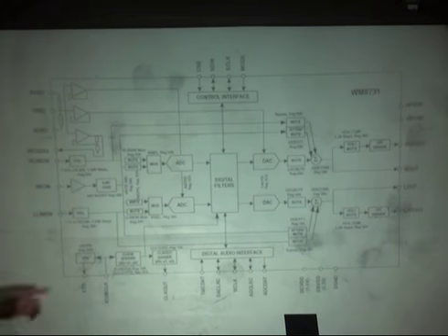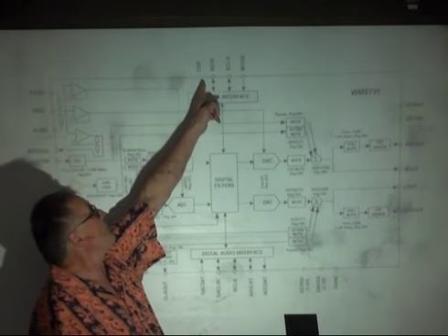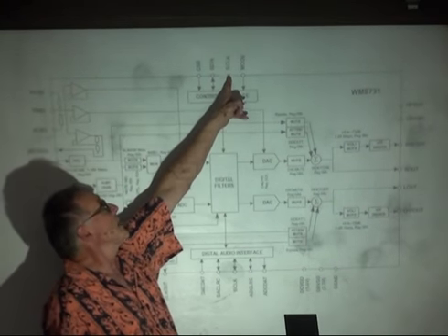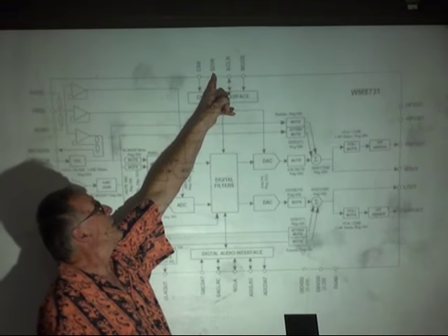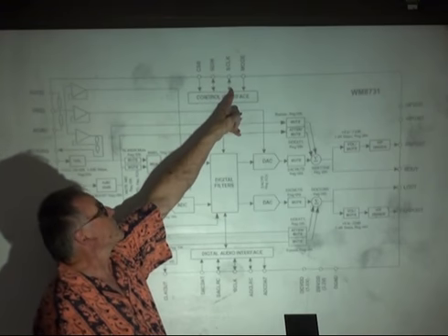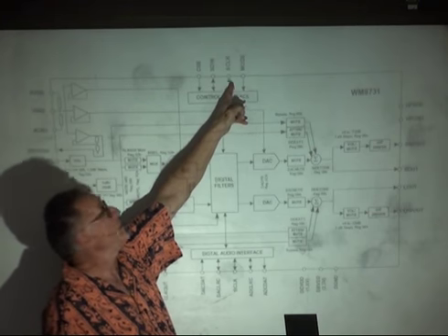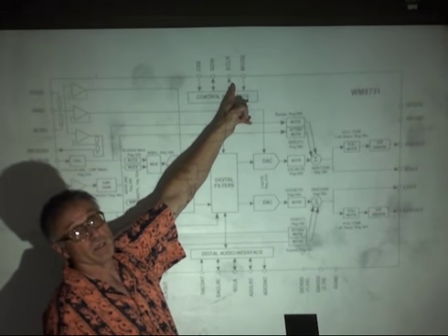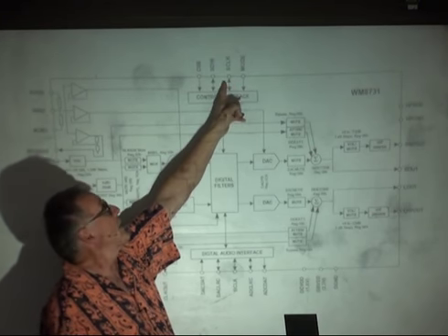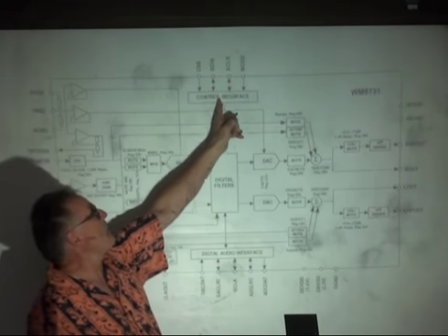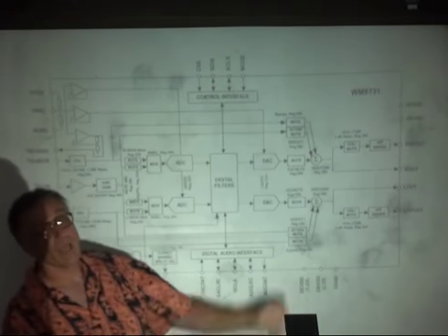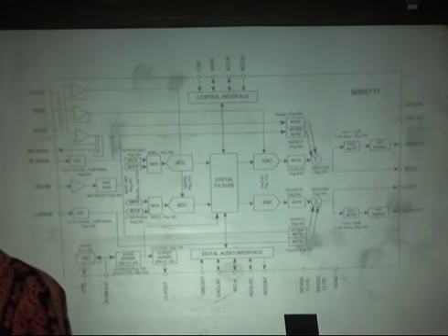And the connections on the top, S clock and data in, are bidirectional ports. In this case, we're going to use the FPGA to determine the S clock, and then the FPGA and the control interface are going to have a dialogue over the two bidirectional data bus, 1 bit, it's a serial data bus, to set up this chip.